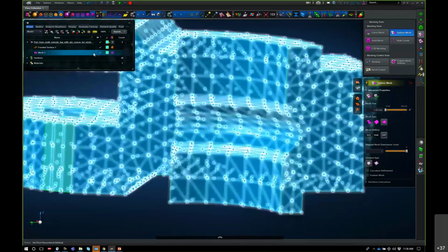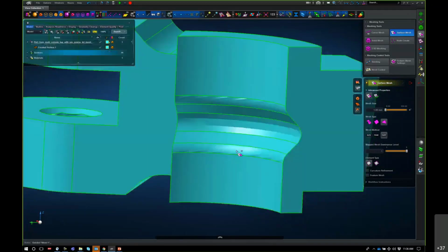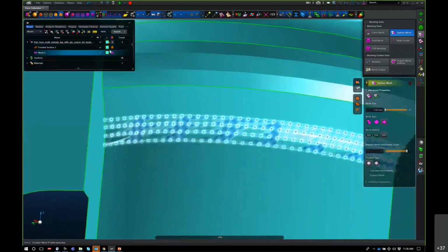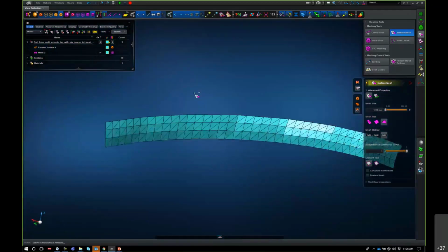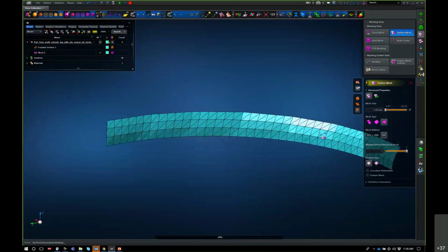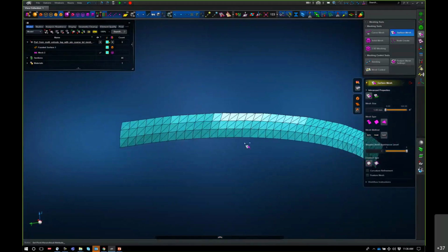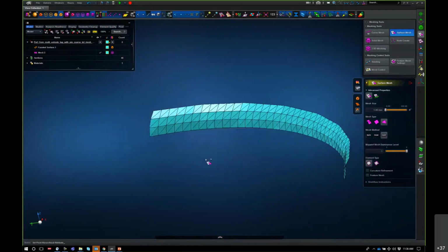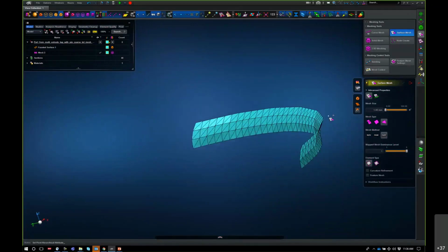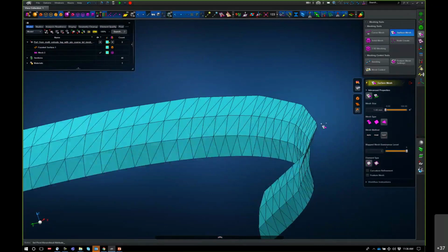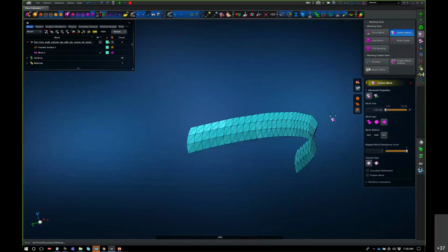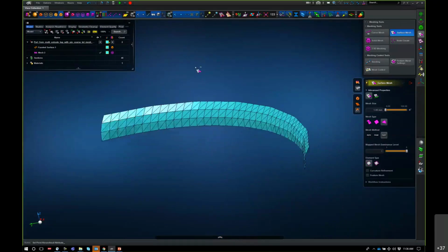Let me delete my mesh here so I can make my point very easily. Turn on very smooth mesh here. You can see some faceting that's happening. It cannot mesh on a curvature that doesn't exist in the definition. Because this wasn't smooth, you can definitely see the faceting. True for all facet bodies in general.